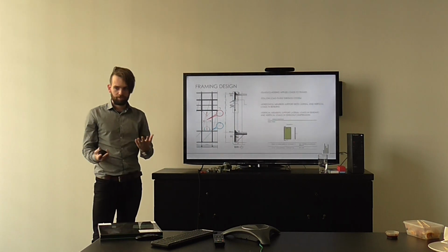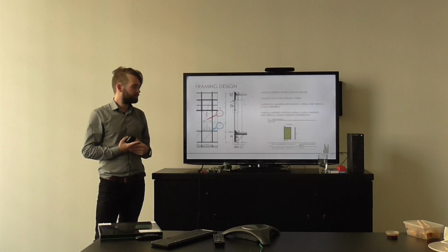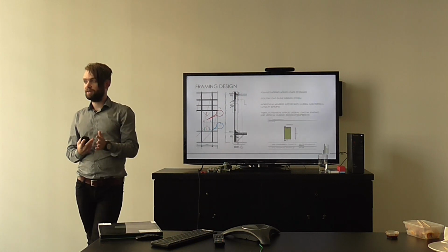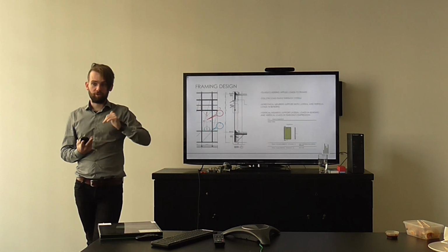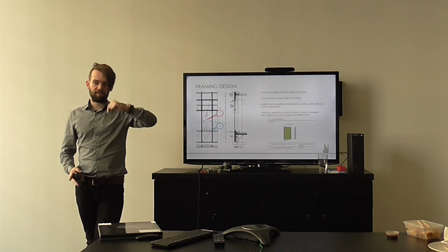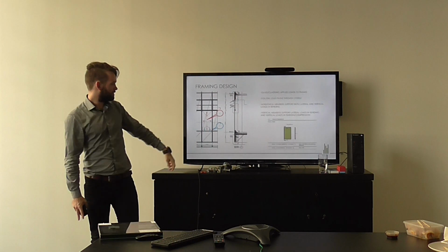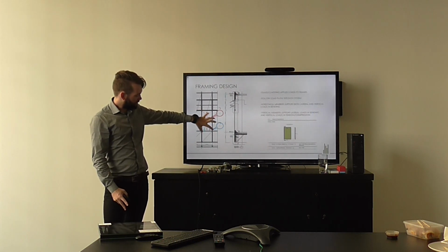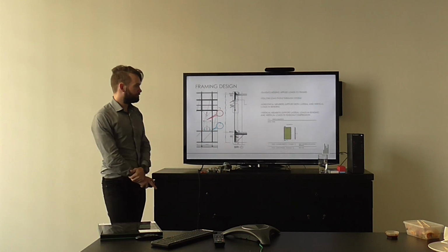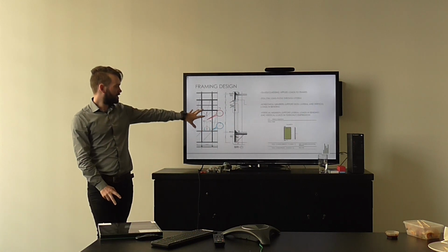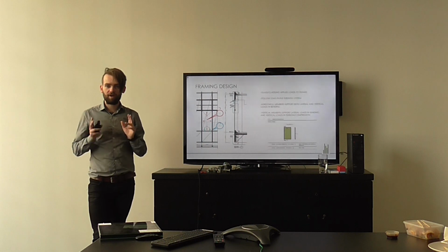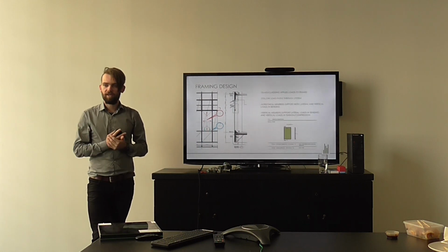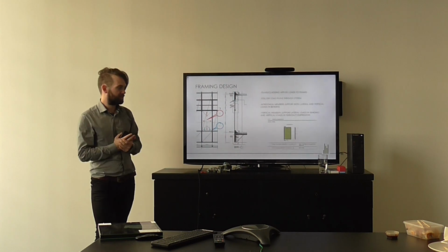Our mullions, or vertical members, posts, whatever we may have, take the lateral load from the glass and wind, as well as the vertical load from the transom, but they take that in either compression or tension. If you imagine the load comes to this transom and it transfers back to the mullions, which are in turn bracketed. So for these different framing sizes, probably the major driver with framing is deflection, and trying to make sure that that is within acceptable limits.